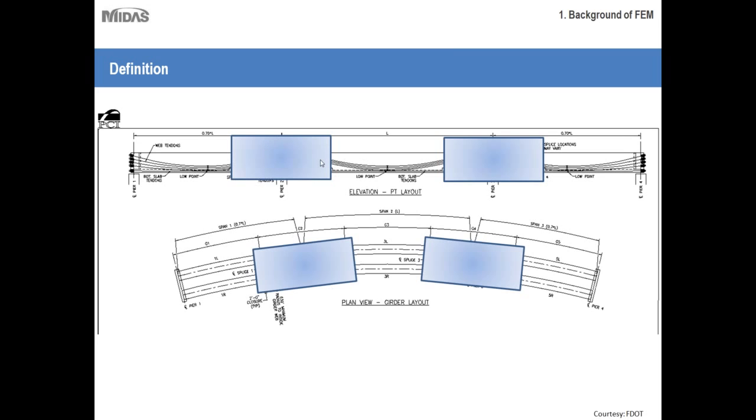In these zones you have to apply the lid slab on top to cover the U girder opening and provide enough stiffness to the section to avoid any kind of torsion in the segment, and give it its stability. Because after this stage we will be doing the post tensioning and applying the deck slab on top of it.